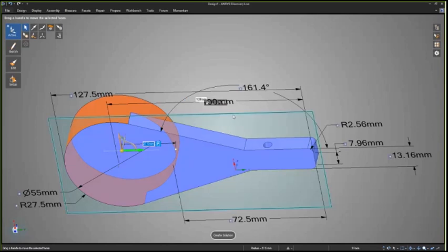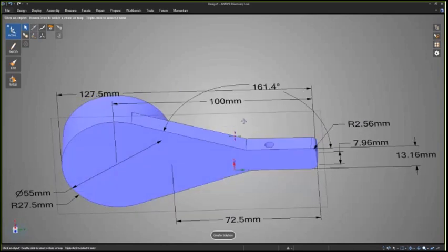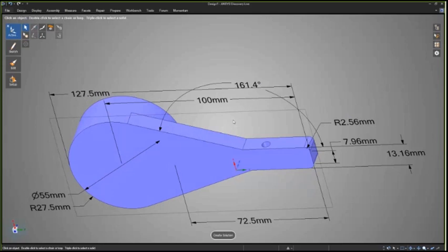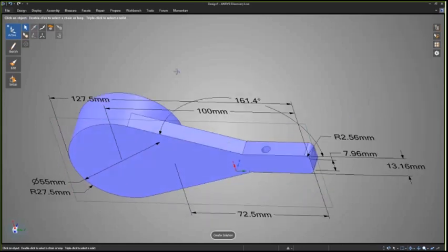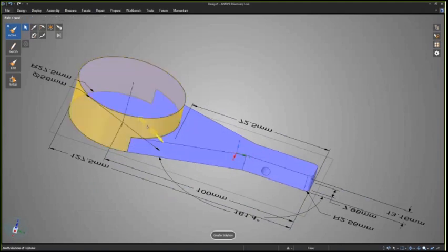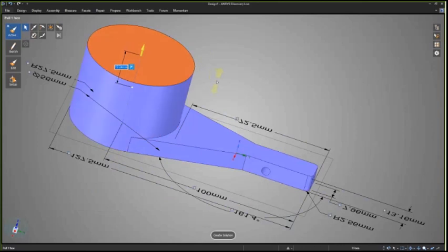or whatever value I need. So parameters, they often say that direct modeling is not parametric, but the real truth is that direct modeling is more parametric than typical feature-based modeling, because you can only use the parameters that you initially added to those features. I could add any parameter. For example, if I care about the surface area of this face, when I pull this face up and down, you could imagine that the surface area is changing.